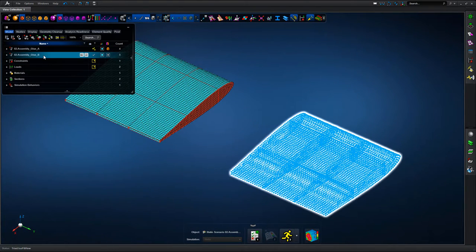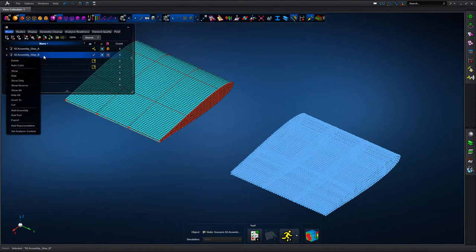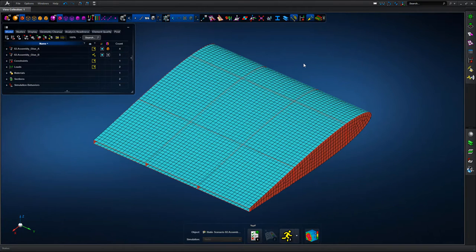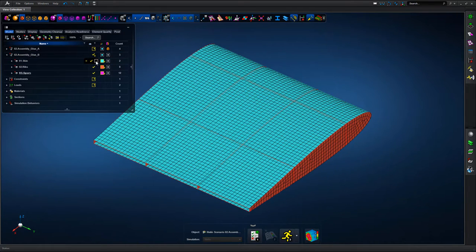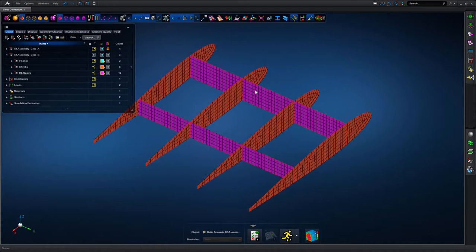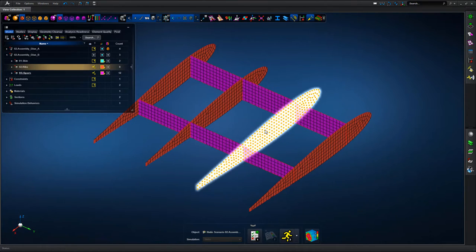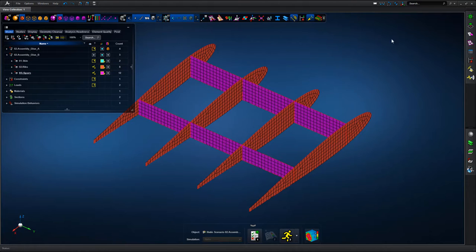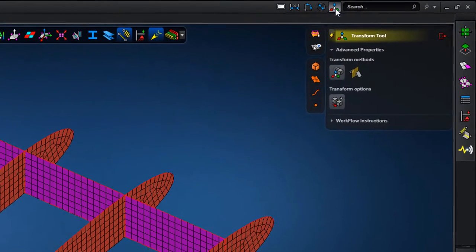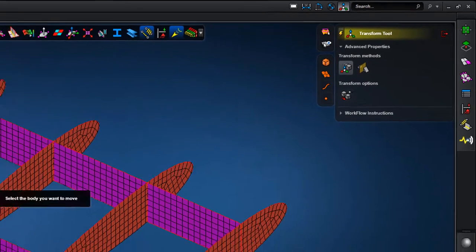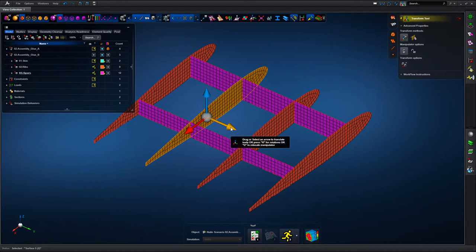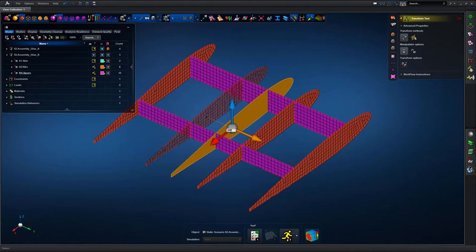Okay, so moving on to the second approach, so we're looking at a different configuration. So effectively we've copied the original wing box to a different position in space using the transform tools, and you can see the original definition, so a copy of the original definition, 2 spars, 4 ribs. So what we're going to do now is reposition the ribs and reposition the spars to allow us to understand model response in terms of the comparison or trade study between the two different designs.